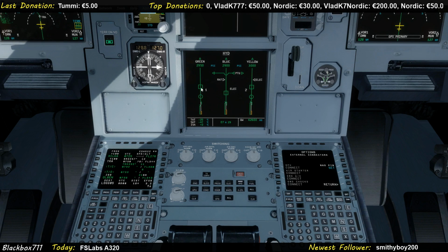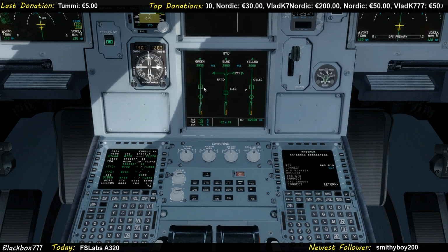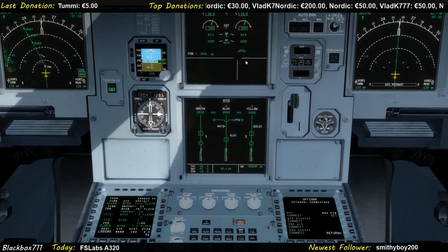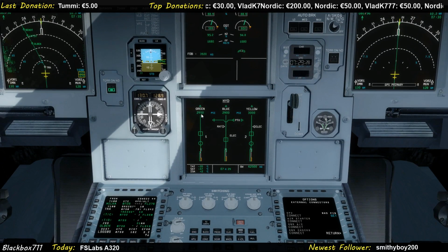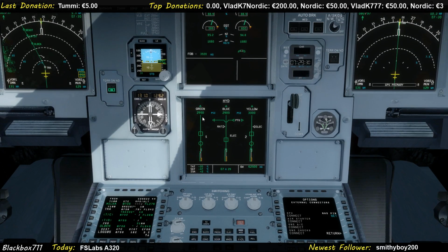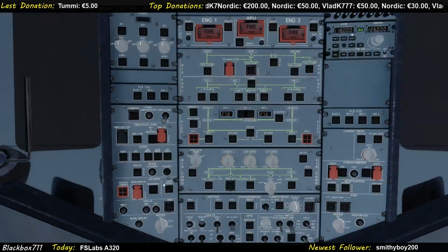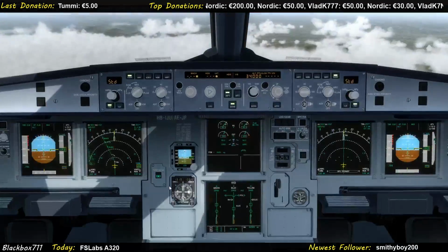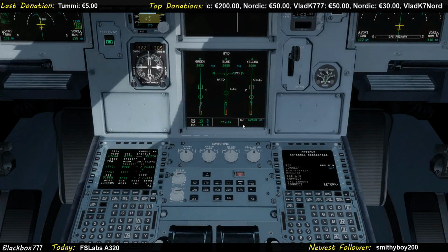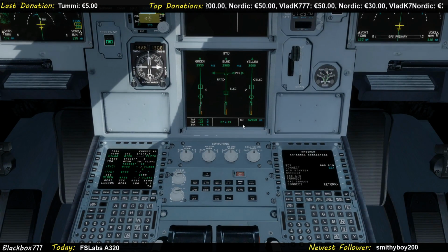If the engines are completely damaged, like in the Sullenberger case in the Hudson landing, then if the N2 rotation just goes below, say, like 5%, the pressure will drop, and then you would only have the blue hydraulic, which comes from the RAT, the ram air turbine, the little propeller that drops out when both AC buses get powerless.